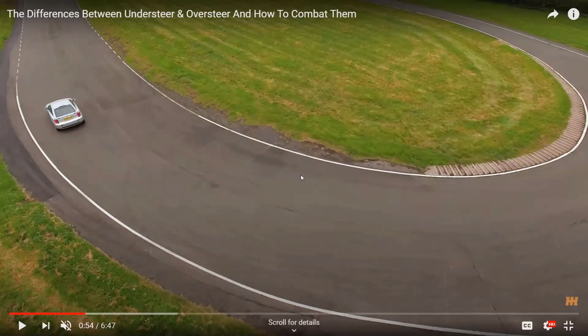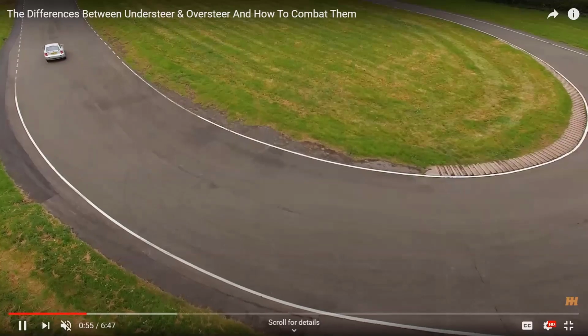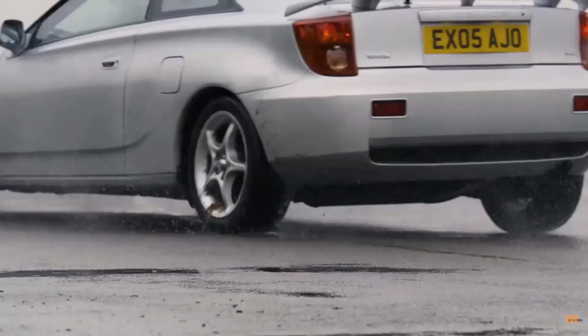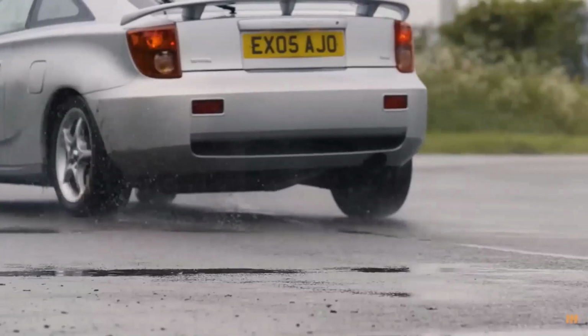If you are making the front axle 80% and the rear axle 20% braking, the rear end of the vehicle will lift up to a certain limit, and the load will be more concentrated on the front axle. So even if we make a steering change, the vehicle won't accept it, and it will keep on moving and tend to understeer.